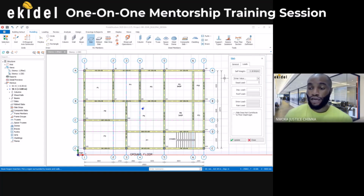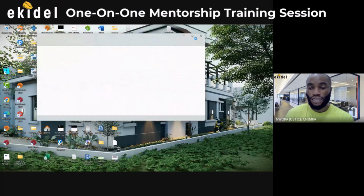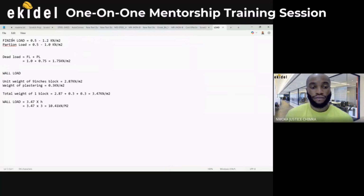So for example, let me minimize this and open up these nodes here. What gives you your dead load value is finishing load plus partition load. Can you hear me? Yes. Okay, yeah. And then finishing load basically ranges from 0.5 kN per meter square to 1.2. That is in my country here. And also partition load ranges from 0.5 to 1.0.